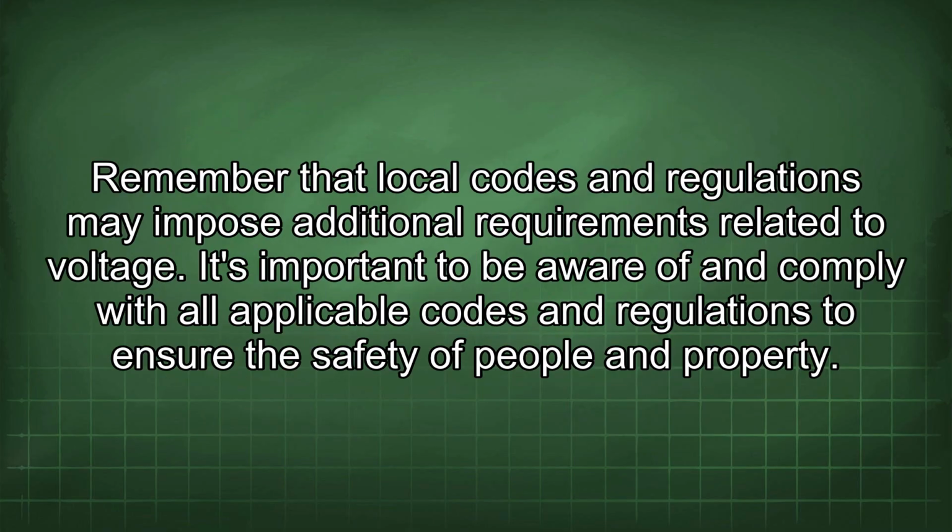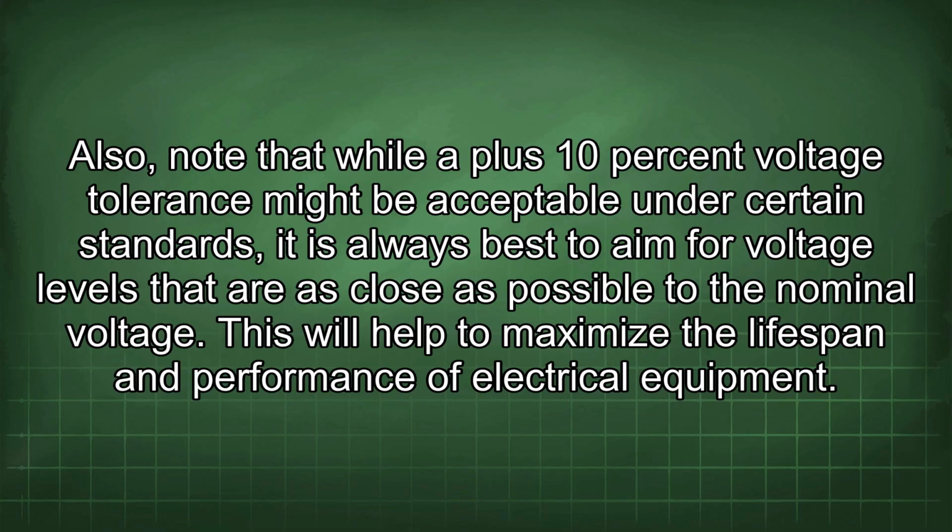Remember that local codes and regulations may impose additional requirements related to voltage. It's important to be aware of and comply with all applicable codes and regulations to ensure the safety of people and property. Also, note that while a plus 10% voltage tolerance might be acceptable under certain standards, it is always best to aim for voltage levels that are as close as possible to the nominal voltage. This will help to maximize the lifespan and performance of electrical equipment.